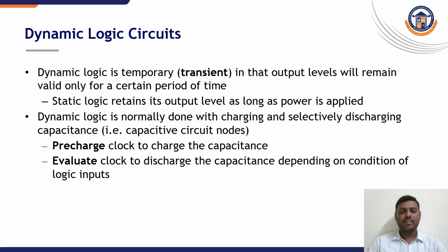So here we are going for dynamic logic circuits. Dynamic logic circuits work based on the pre-charge and evaluate phases. In the pre-charge phase, the capacitance of the inverter is charged and it holds the value. In the evaluate phase, the capacitance selectively discharges based on the input values.